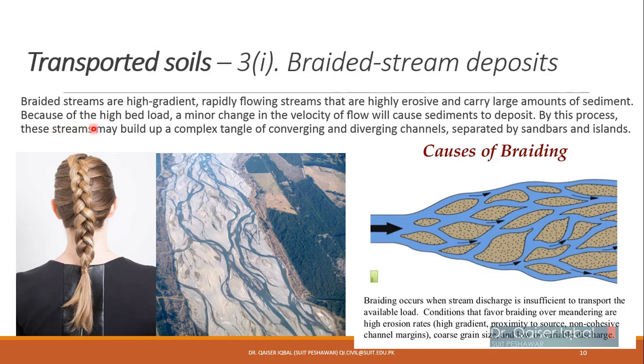Because of this very high bed load, the particles carried by the water are known as its bed load. A minor change in velocity, if you reduce the velocity of the flow by a little bit, will cause the sediment to deposit, because its velocity will no longer be very high. It will not be able to carry the heavy particles, so it will deposit them in the area where its velocity becomes less. By this process, these streams may build up a complex tangle.